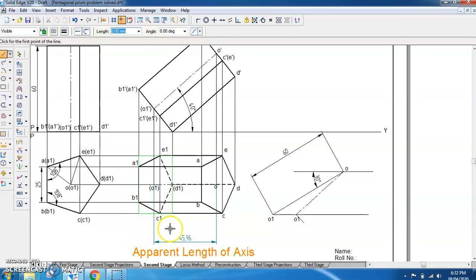Now when we have got this rectangle, we have got some of the points of this pentagon on these lines. If this is the rectangle which we have drawn, then A1, B1, C1, D1 and E1, all five points are on this rectangle. Now to get this rectangle, we have to get the distances from O1. From O1, the distance from here to here is 11.6, and here to here it is 13.67.